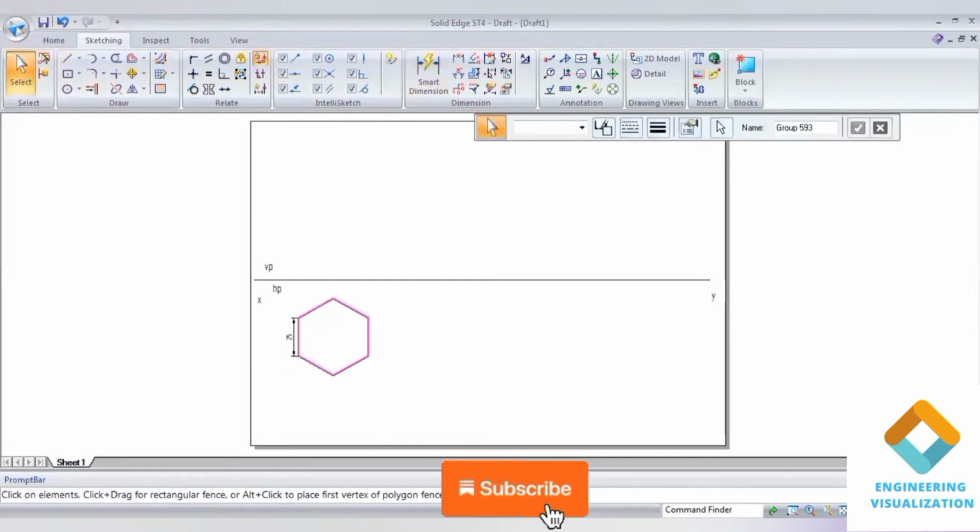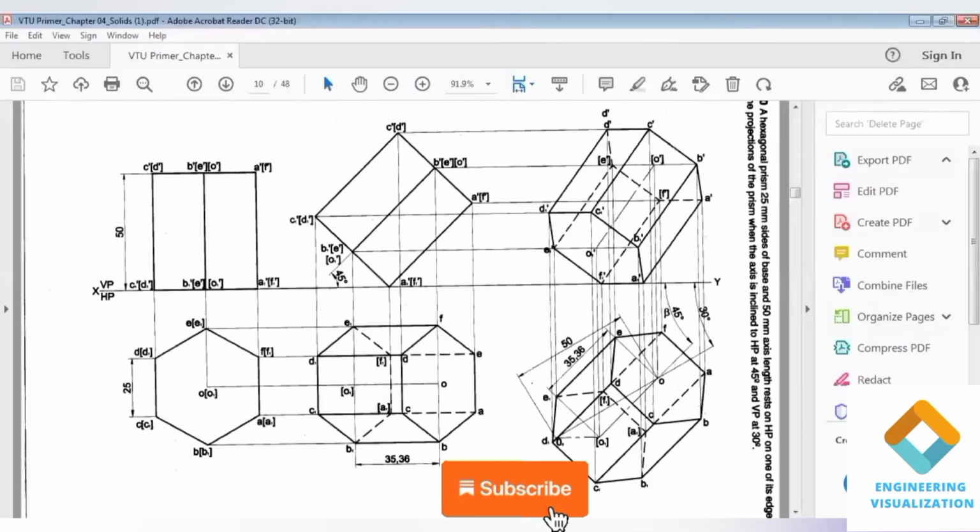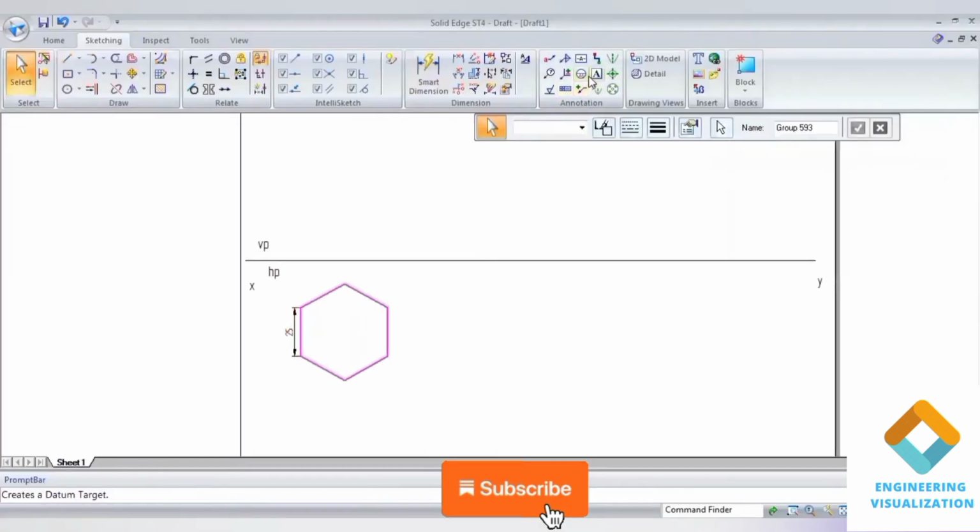Now write the notation, top view and bottom view notations. Top view notations are written with ABCD and bottom face notations are written A1 B1 C1 like that, but it should be written within brackets.